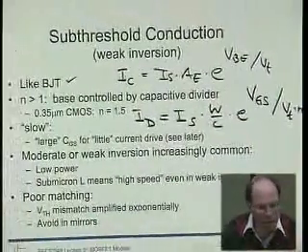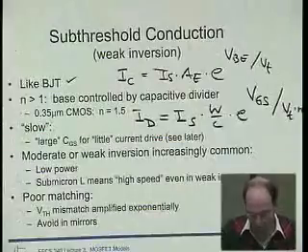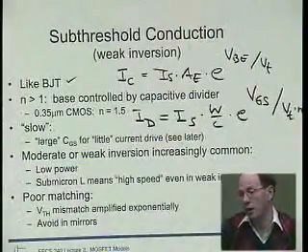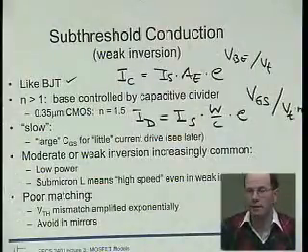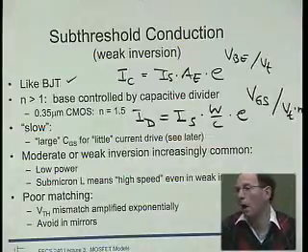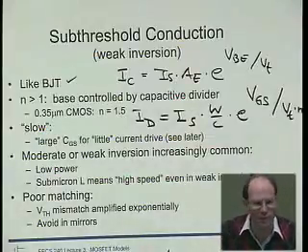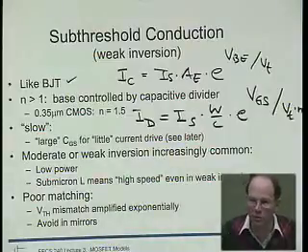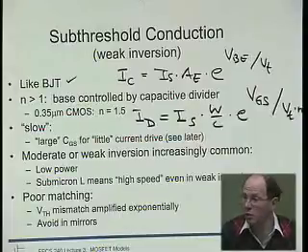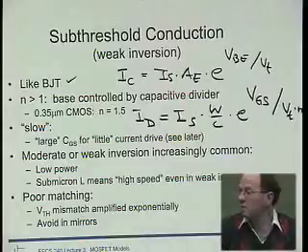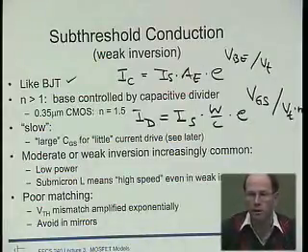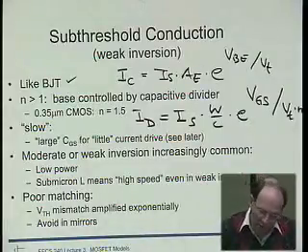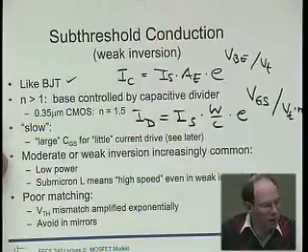Why is it slow? Well, because in order to make VGS very small, suppose that I want to run a certain amount of current, let's say 100 microamps, and we'll see why I might want to actually run 100 microamps, right? Then I need a big transistor to keep VGS low. Well, a big transistor means that I have a huge CGS. A huge CGS means that there is a capacitor somewhere in my circuit that's going to slow things down. So there's going to be a trade-off, and we're going to study this trade-off.